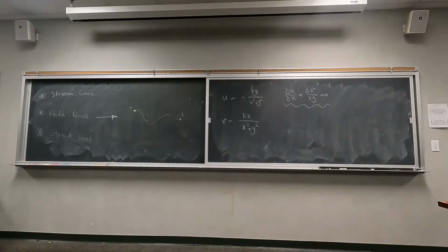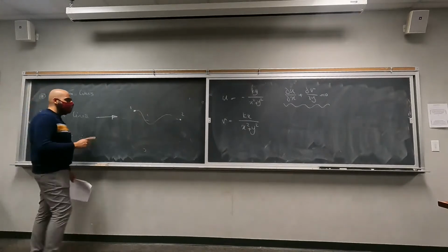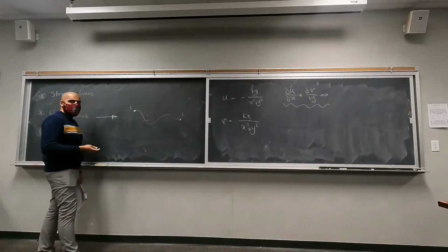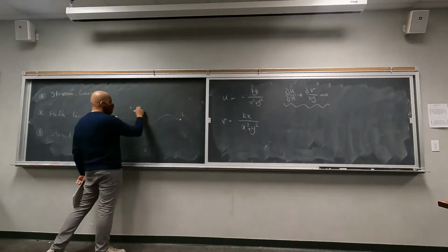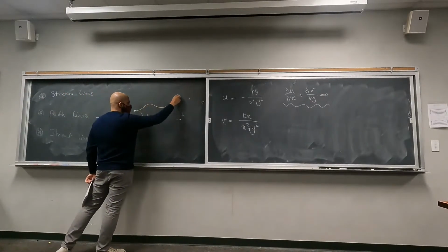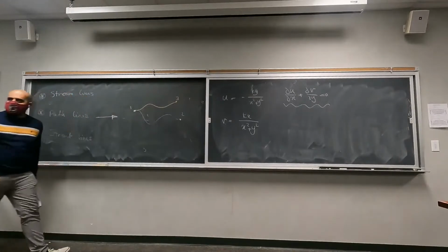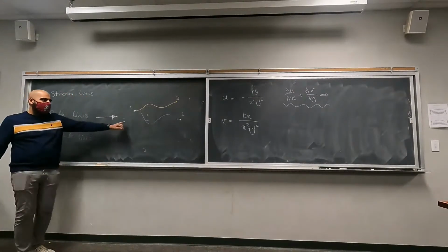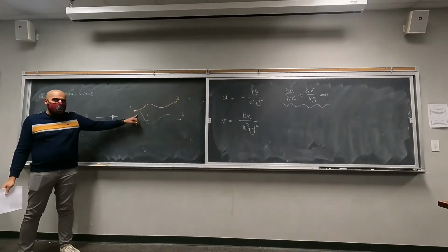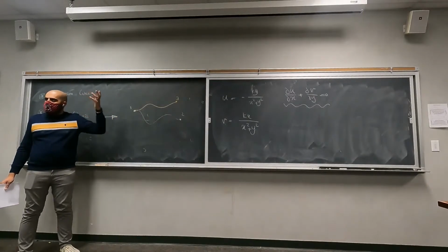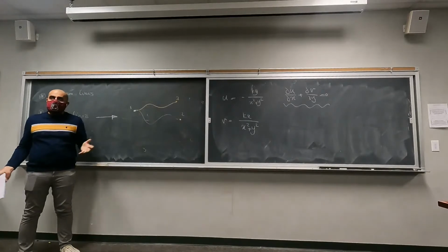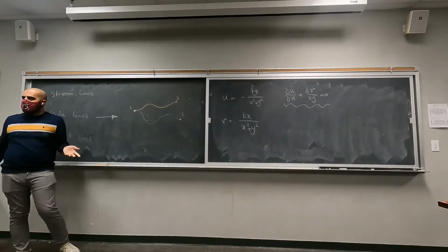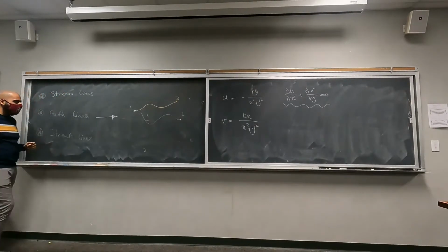If we are dealing with unsteady flow, path line for two different particles that are passing through the same point at two different times is going to be different, because the flow is unsteady. So the forces that are going to be applied at this location are going to change over time, or partial rho partial t, partial whatever partial t is not 0. Does this make sense? Path line.